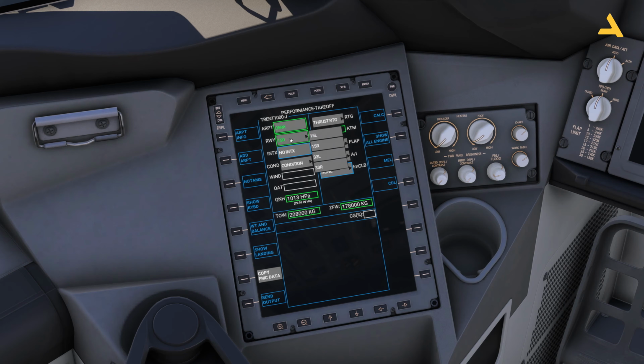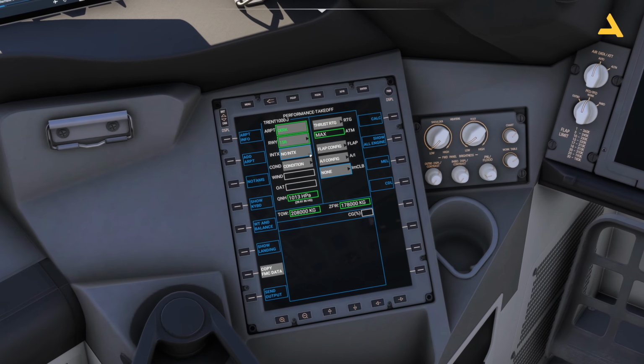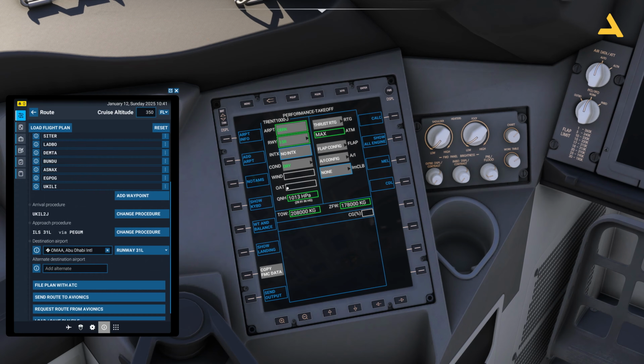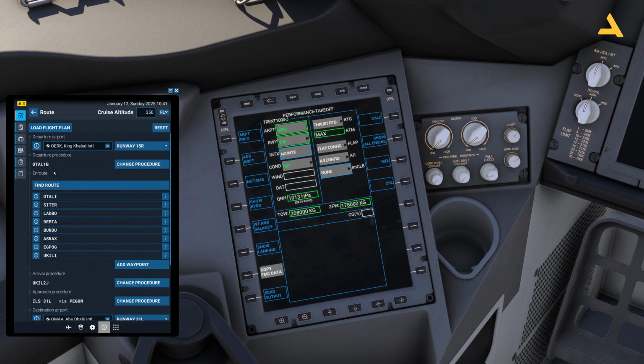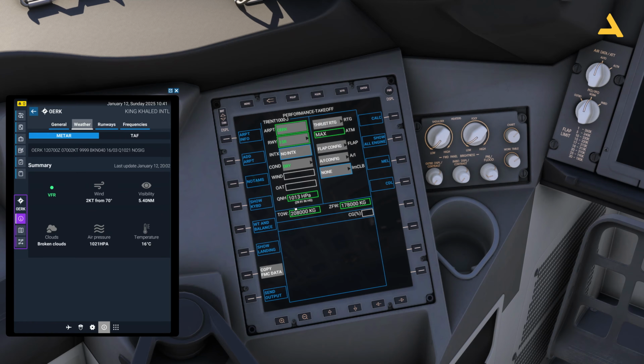Airport OERK runway, you can select it. It's already there. It's same. If I go to departure, arrival, yeah, 15, right? That's right. That's it. So no intersection, condition is dry. Let's get the wind and the outside temperature. So go to this option, and in the weather, you will get the wind, 70 degrees, 2 knots. So 70 degrees /2. And the outside temperature is 16.